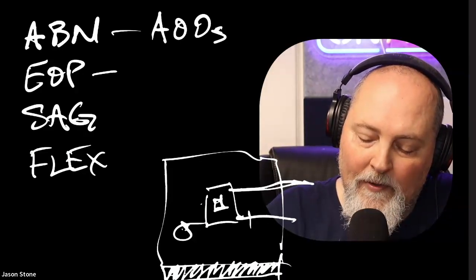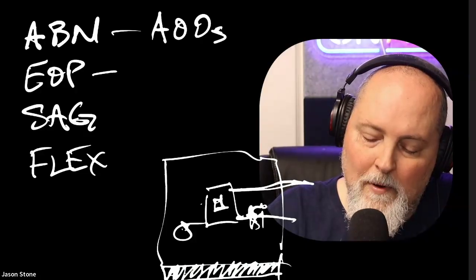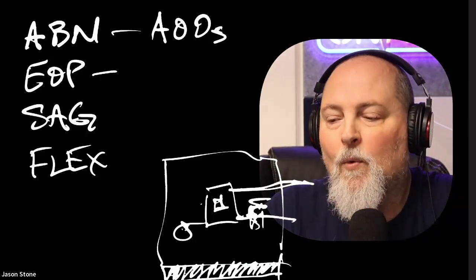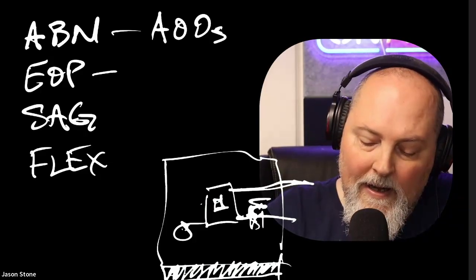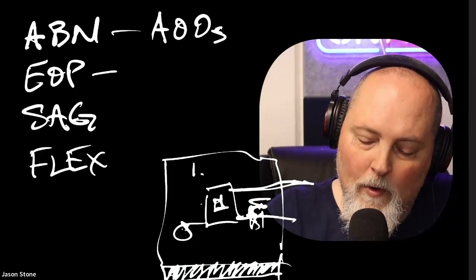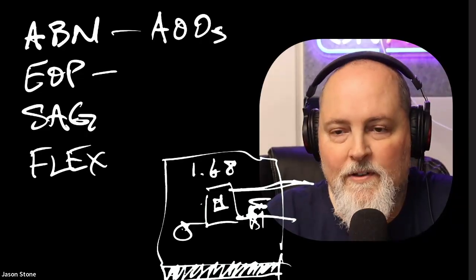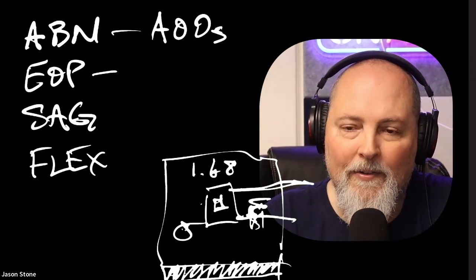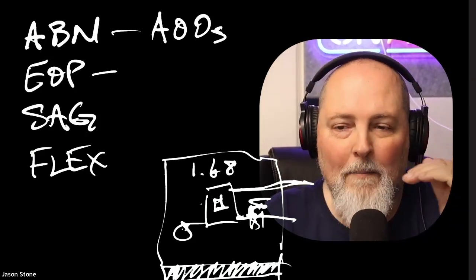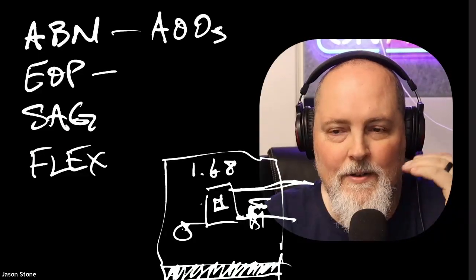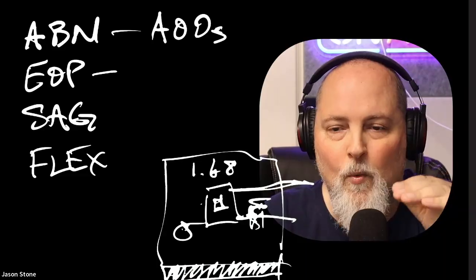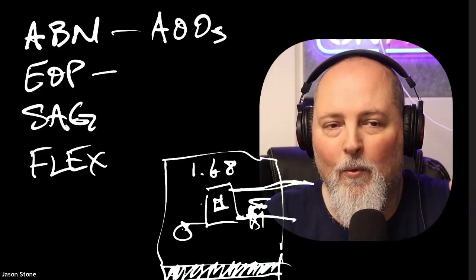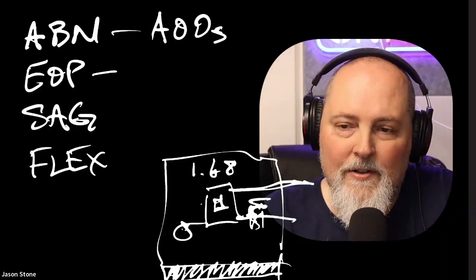And so let's say with all this equipment, we have valves. So let's say a valve blows apart and is starting to put a bunch of steam into primary containment, into the dry well. Well, then pressure starts going up. And as pressure starts going up, if it hits 1.68 pounds per square inch gauge, PSIG, then we have an entry condition into our EOPs. So our EOPs have entry conditions, for example, low reactor water level at plus 13 inches, high drywell pressure, 1.68 pounds. Hey, we should have had a scram and it didn't scram, so we enter the EOPs. So there's entry conditions that put us in there.